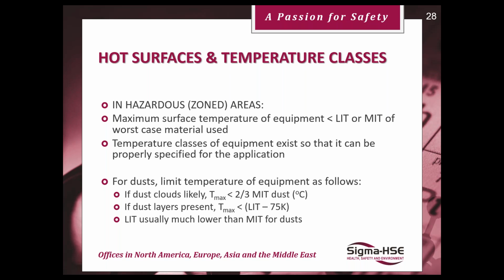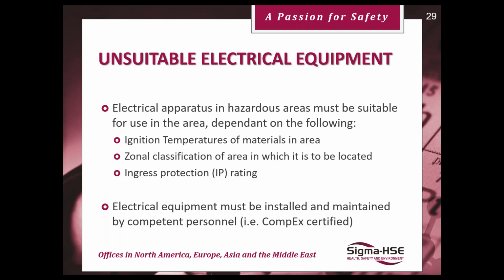If we're looking at electrical ignition sources, then of course we can ensure that we use ATEX certified equipment specifically built to reduce the probability of ignition. And ATEX certified equipment must be installed, maintained and inspected by specifically competent personnel to keep it effective. We've got to make sure that we look at it occasionally and take appropriate action to keep it effective.